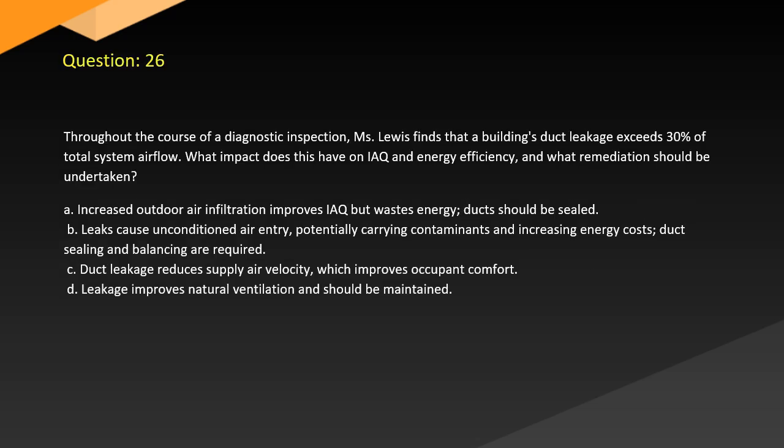Question 26. Throughout the course of the diagnostic inspection, Lewis finds that a building's duct leakage exceeds 30% of total system airflow. What impact does this have on IAQ and energy efficiency, and what remediation should be undertaken? A. Increased outdoor air infiltration improves IAQ but wastes energy. The ducts should be sealed.